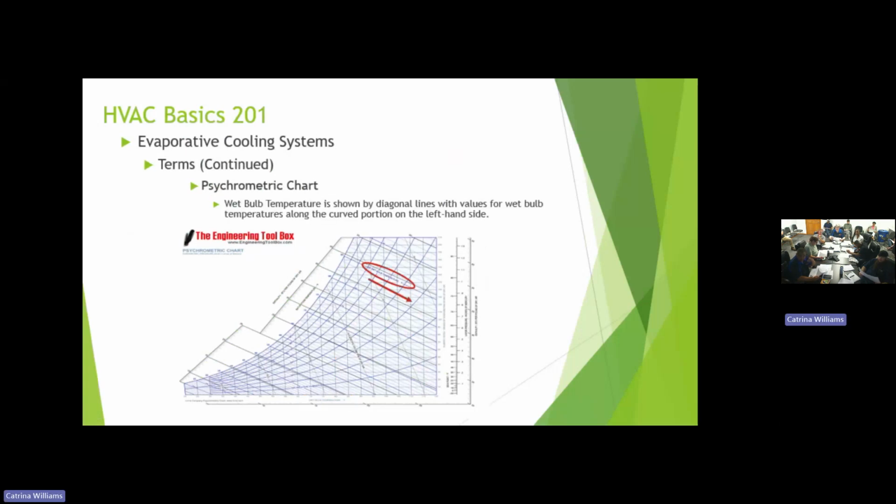We're going to go into wet bulb, and those are the diagonal lines, 45-degree diagonal, coming in from the top. Here is the temperature, wet bulb, going down the graph there. Can anybody see the ones going down to the right? Yes. That's your wet bulb.